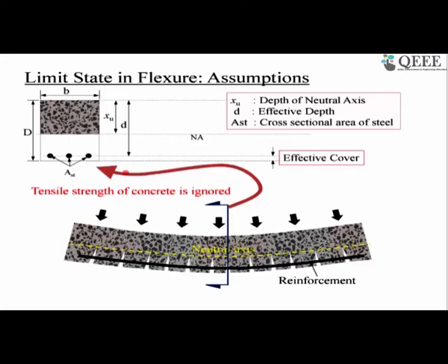How much cover you give in a structure depends on many things. It depends on what kind of structure you are designing, whether it is a beam, slab, or column. Every structural component requires different cover. It also depends on the environment the structure is subjected to. If the structure is subjected to a very adverse environment, which has potential to corrode the reinforcement, then we need to provide more cover.